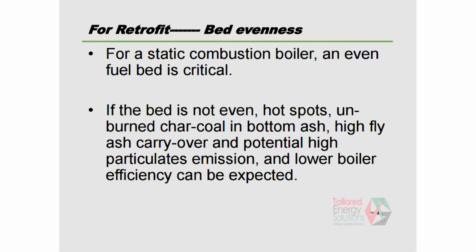The bed evenness: if the bed is uneven, what's going to happen? The air is going to go to where there is less fuel, so that you get a very high unused airflow, resulting in lower boiler efficiency, and blowing some of the ash particles towards the chimney, resulting in higher particulate emission.